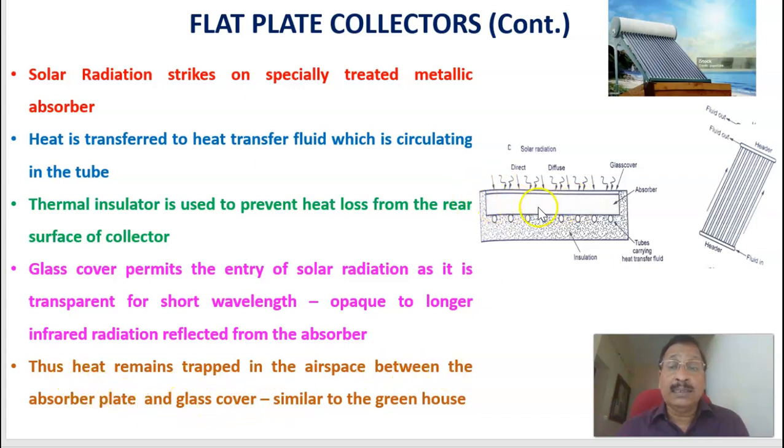Here, between the absorber plate and the glass cover, the heated air is being trapped, and that heat energy is transferred to the heat transfer fluid by this mechanism, similar to the greenhouse effect. Therefore, that thermal energy is transferred to the fluid that is passing through this. That is called the flat plate collector.